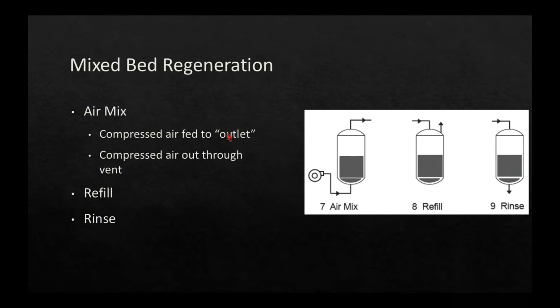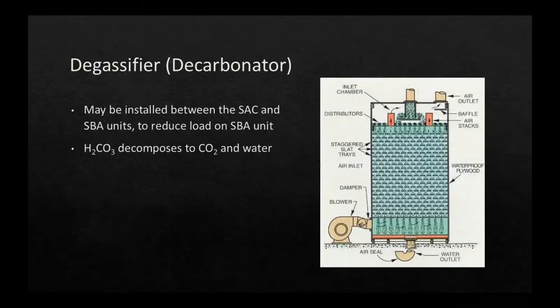We often do get a certain amount of carryover. If we've got a drum type boiler with the right kind of steam drum internals, maybe we get 99.5% dry and saturated steam entering the superheater. But what about that 0.5%, or that 1% of moisture? Well, it carries impurities with it, and it doesn't take long for impurities to build up on the superheater, and then we get a failing superheater.